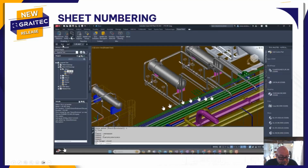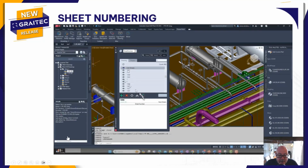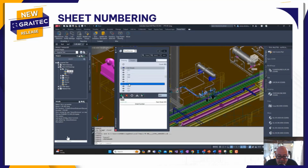So here we are again. Let's have a look in here, and here's our line manager. I can come in and select a particular line. At the moment, you can see it's zoomed in and selected the pipeline in the background. I've got my sheet number set to 001. I add a new sheet in, and as you can see, that entire line has now been put onto one sheet.